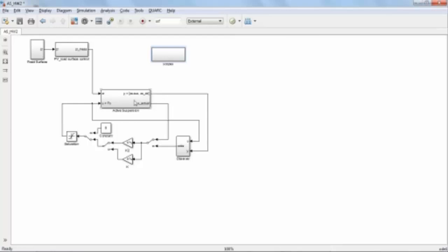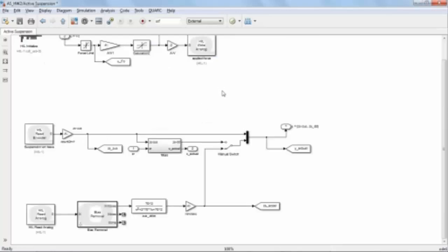Now, this is basically how we can do the observer design. Since we have the chance to actually estimate our system state with filters, we could also choose not to use our accelerometer data for our car acceleration, but use a second order high pass filter to get our acceleration from the encoder readings only.